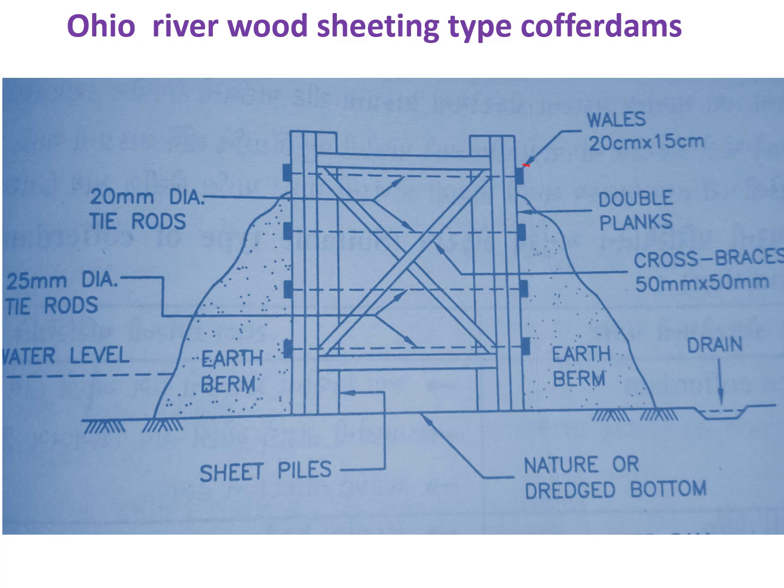Initially these are the wells at around 1.5 meter which are fixed. Then here these double planks are there, 1 and 2, and after that it consists of the sheet pile. So this is sheet pile. Here two layers of sheet piles you can see, and these are called tie rods.